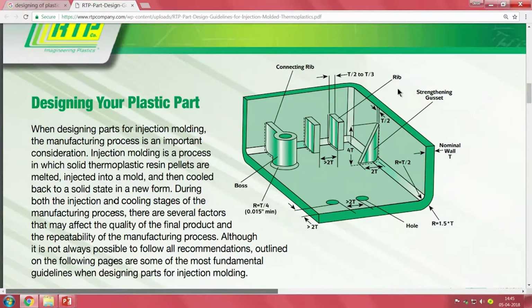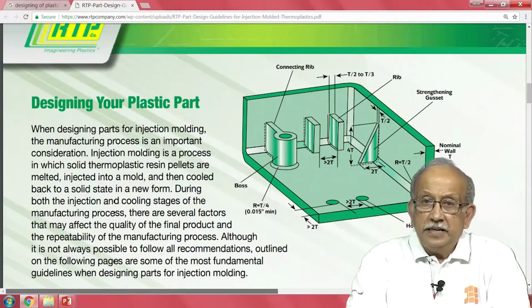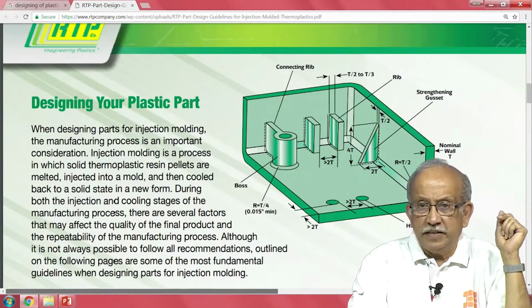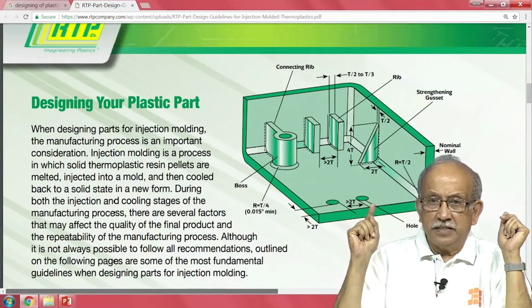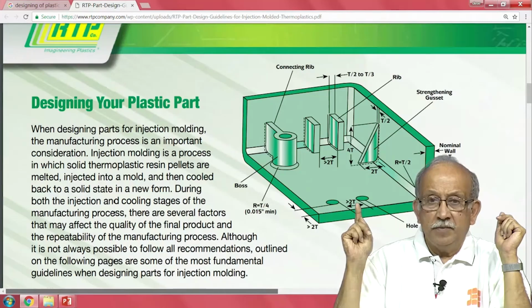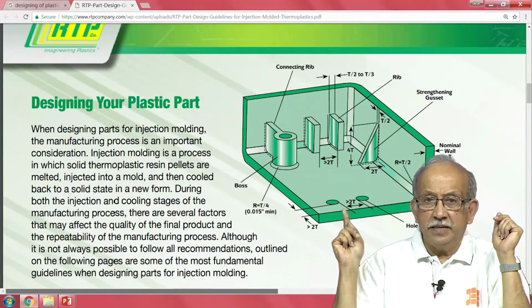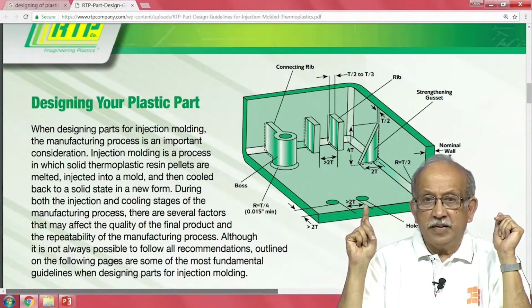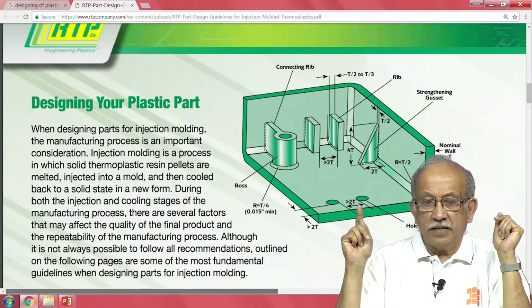And this picture has a lot of detailing and data built into it. One of them you see here is everywhere they have given small things saying how far a hole should be from the edge, and what the spacing should be between two holes, because material has to flow around the hole and go to the other one.